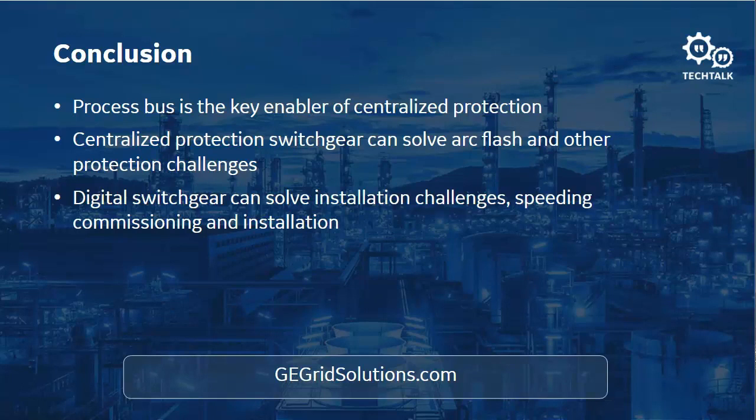That dispersion limit, I am not 100% certain of for the MU320. I remember from our brick product, which has a similar transceiver on it, we could go up to 500 meters before we had problems with that dispersion limit. If we're going from a switch to an Ethernet network, as long as we supported that Ethernet network, we could have a lot more flexibility on the actual distances.